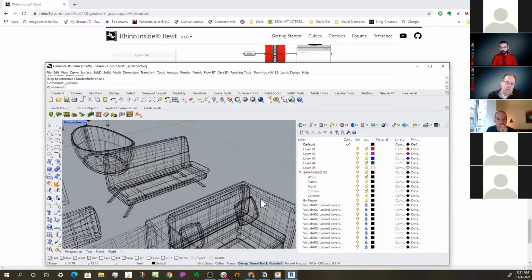If that doesn't work, if we send that geometry to Revit and Revit looks at it and rejects it, then we will try a secondary method of transferring the model, which is we write an SAT file out and Revit reads that SAT file back in.